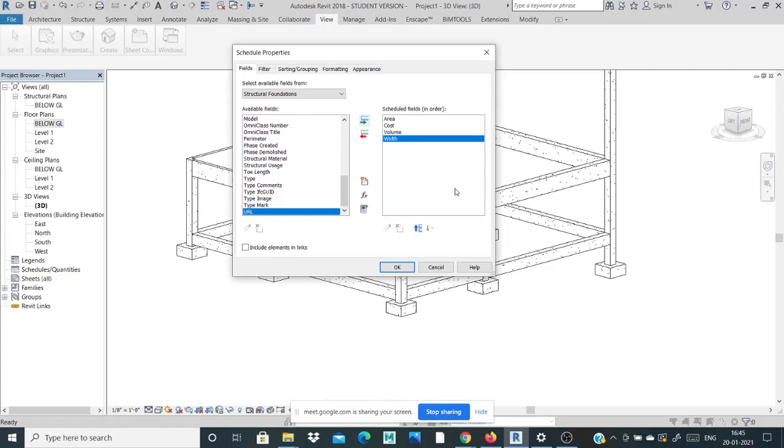Then how to calculate the cost of my footing concrete? Simple. You calculate the volume, and easily calculate the cost like that. Suppose I need 5 meter cube concrete for my footing. You simply tell the RMC 5 meter cube. 1 meter cube of concrete is 18,000.